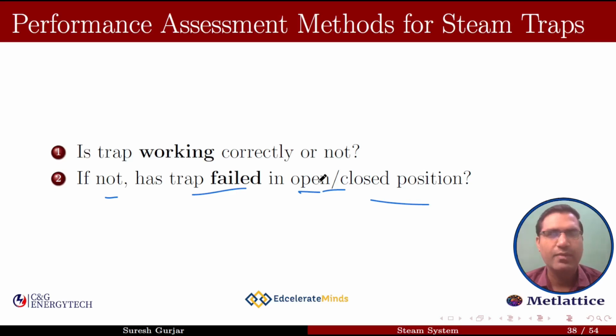capacity. When steam traps fail closed, it means they stop allowing the condensate to pass through. Steam traps that fail closed do not result in economic or water losses, but can result in significantly reduced heating capacity or damage to the steam heating equipment.